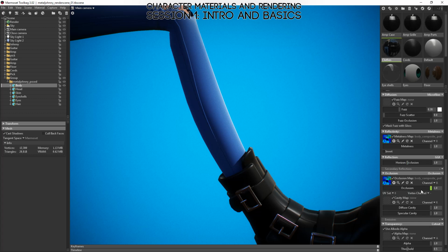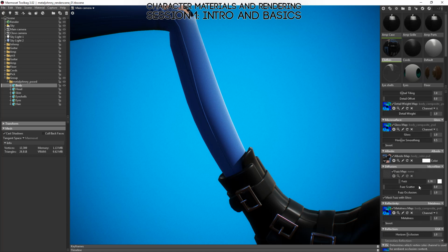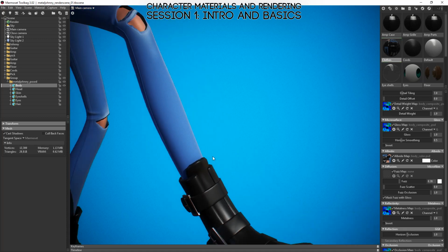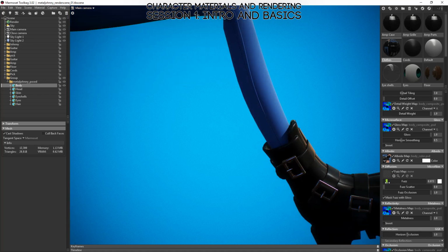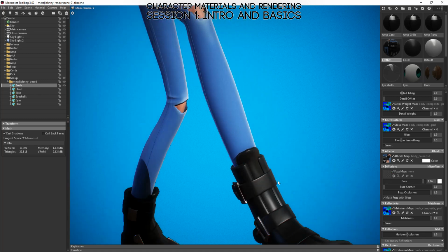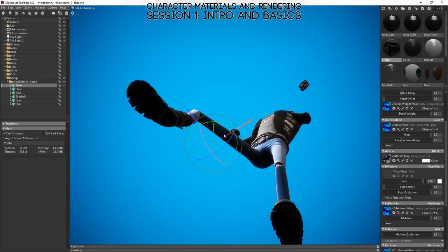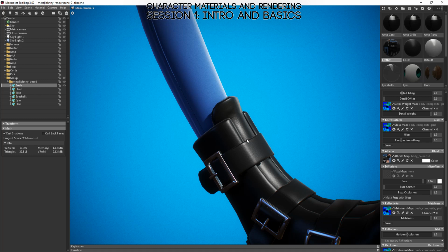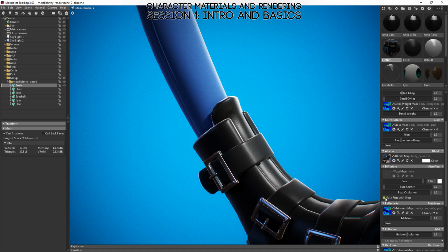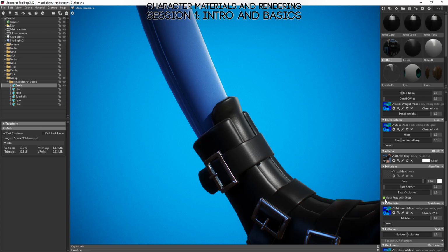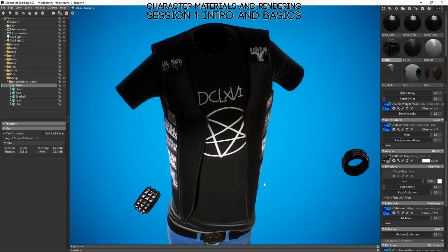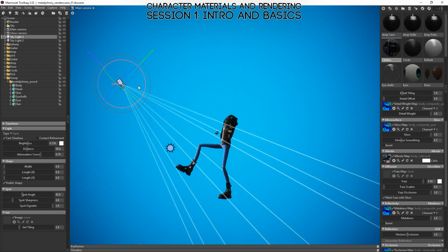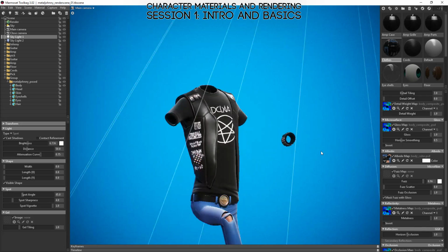Now, in most programs you'll work with, they'll have some sort of cloth shader or the equivalent of a cloth shader where you can get some nice fuzzy effects around the edges, and you can turn that down, turn it up. And in the case of what I'm working on now, with these different materials on the same shader, I can mask the fuzz with gloss. So this is something that's specific to Marmoset Toolbag, but you'll see other similar options in things like Unreal 4 or custom-built Unity shaders. These are pretty common options when somebody wants to represent cloth.